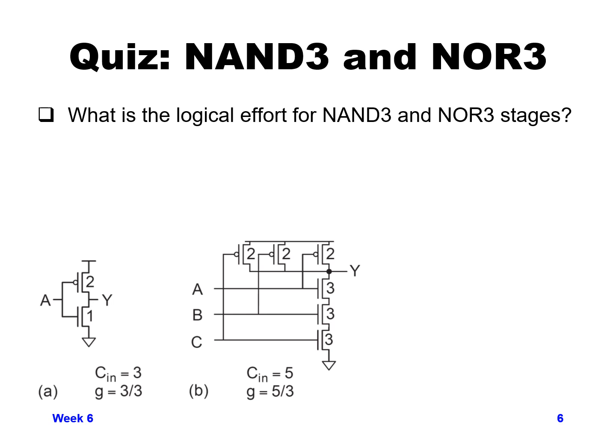If we want to bring the resistance down to the same as a unit transistor, we need to make the transistors 3 times as wide so that the net resistance is the same. So we have size 2 PMOS, size 3 NMOS. That adds up for each particular input, A, B, and C. They have a size 5, 2 plus 3, and so the Cn is 5, and the value of G is then normalized, so it's 5/3.